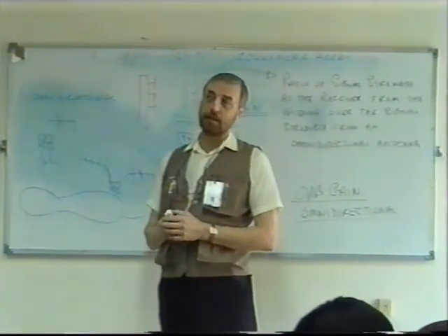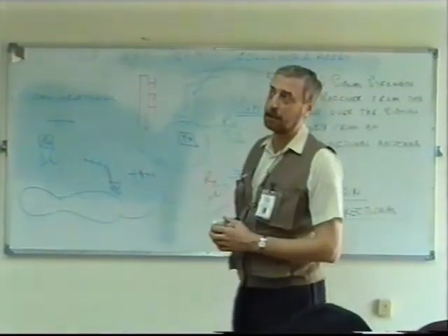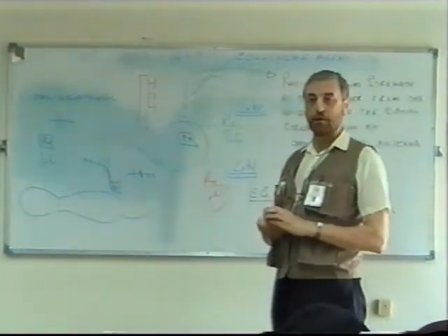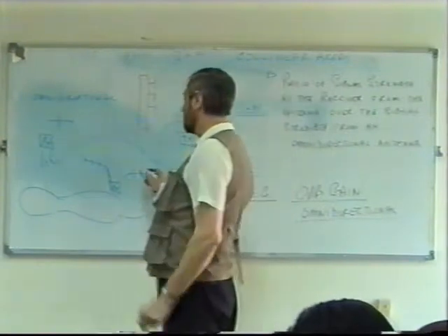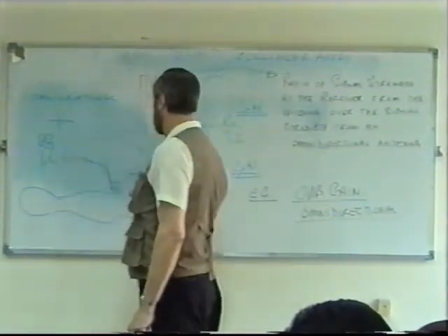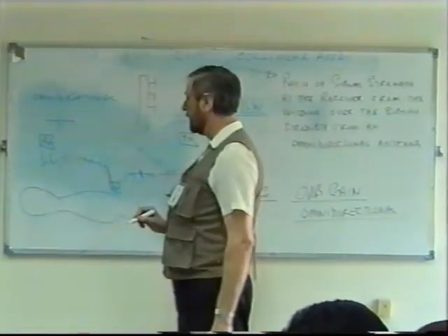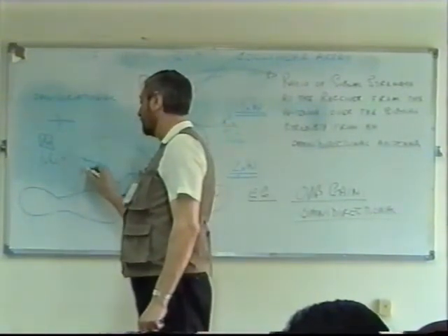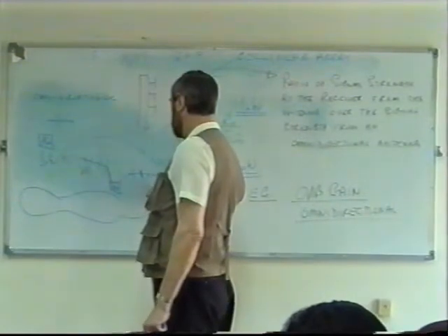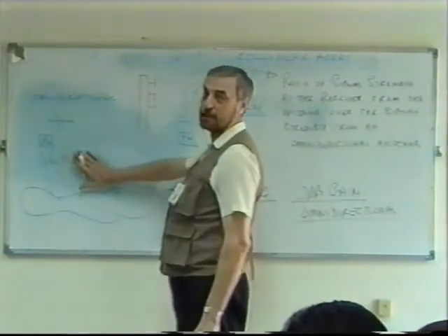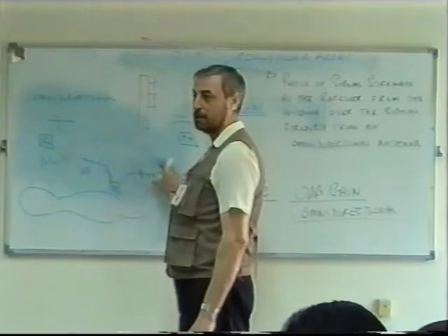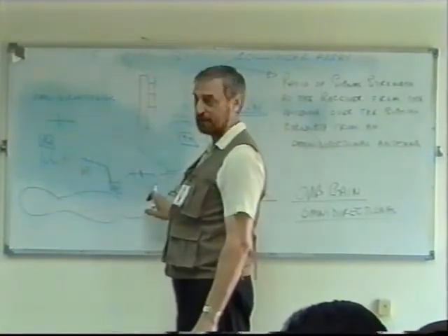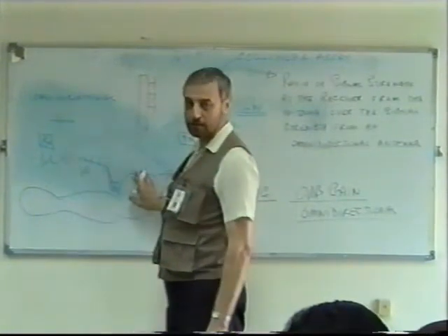You can give all sorts of examples like this. I could ask the question the other way around. I have an antenna system which radiates in two directions, and the gain of the antenna in this direction is 7 dBs, and the gain in this is 7 dBs. Now if I cut out this antenna and put all the power into here, this will go up to 10 dBs. The reason why it doesn't go up to 14 is because all I'm doing is doubling the power, that's all.